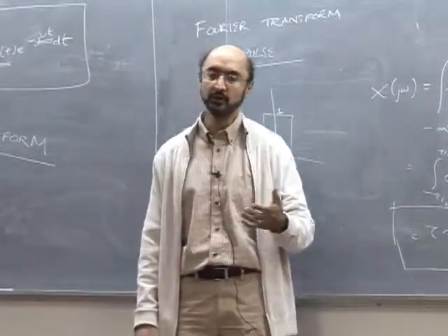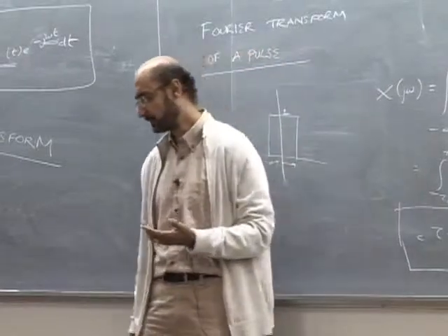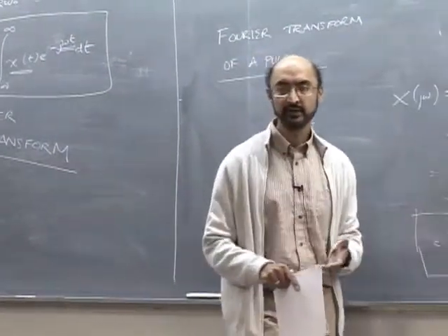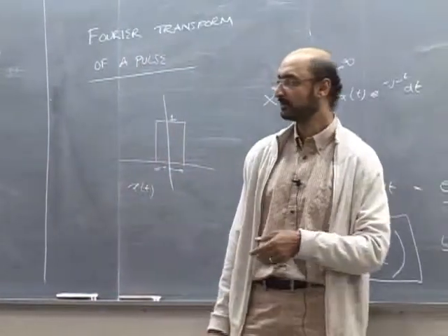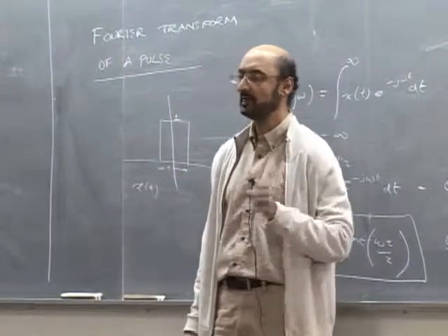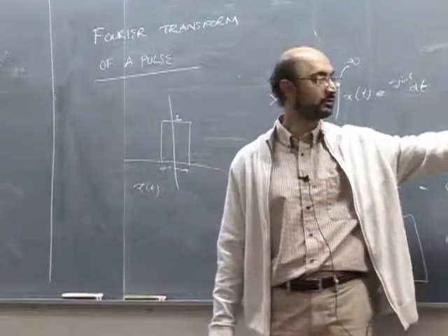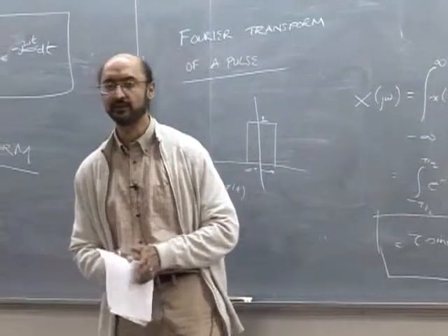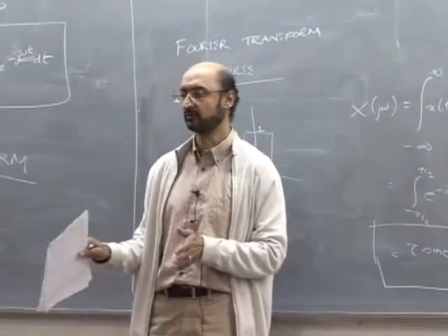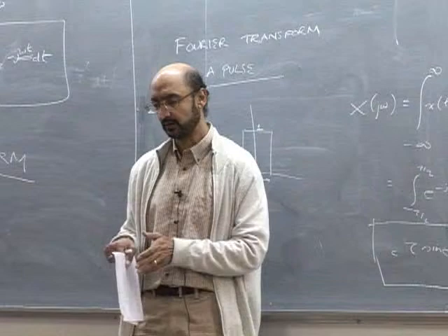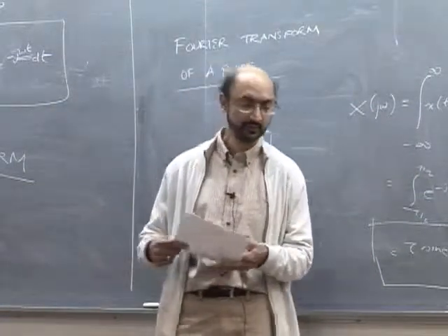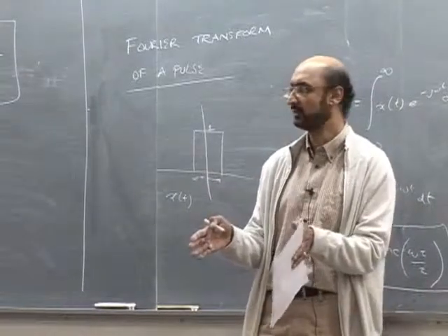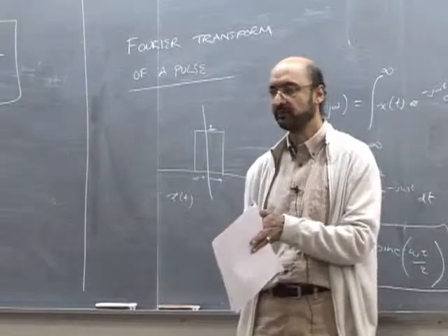And if you look at all modern communication systems, cell phones, Wi-Fi, which are really the 2 main things that are out there, plus pretty much anything else, or Zigbee, you name it, they all use OFDM, orthogonal frequency division multiplexing, because you're getting something for nothing. In some sense, you're getting something for nothing, because spectrum is very expensive. The electromagnetic spectrum is a limited resource. You just have a certain amount, and each piece of it is very valuable.